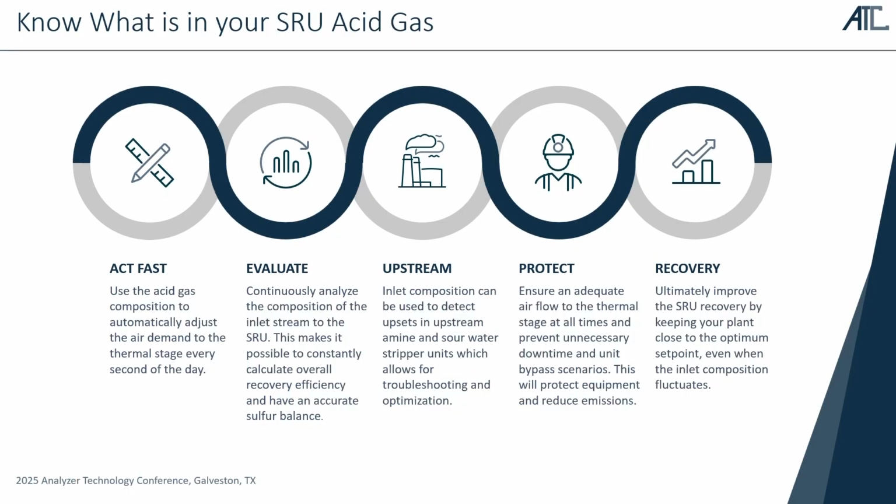So if you have an analytical measurement of what's coming in, what's going out, basically you can close the sulfur balance around the sulfur plant. And basically especially important for people that report on sulfur recovery rather than absolute emissions, you can truly and accurately validate what actually the sulfur recovery efficiency is based on these data.